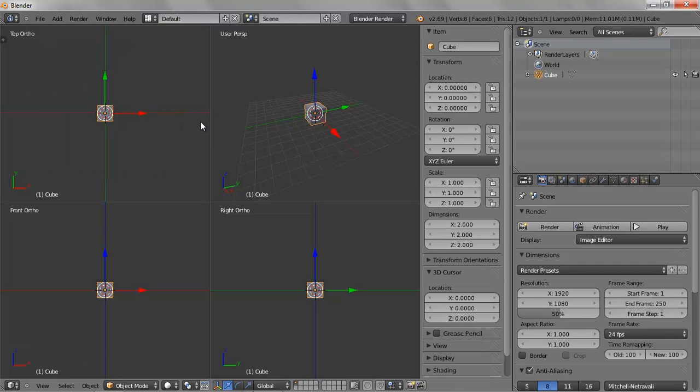Basically you'll see when I create it, the dimensions are right here. So if I want, I can do 1 by 1 by, let's say, 5. Now I've made a leg. If I zoom in on it, it's in the center, which I probably don't want. The other thing is it's currently called Cube, so I can change this to leg